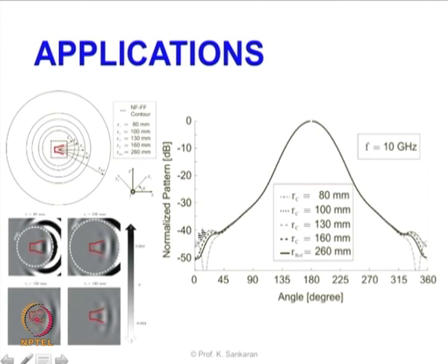So we used this as a way, because what happens is the numerical results for a larger model are used instead of directly using the antenna chamber measurement. Due to the limitations of the chambers, the low level back radiations of the horn antenna are not accurately resolved.